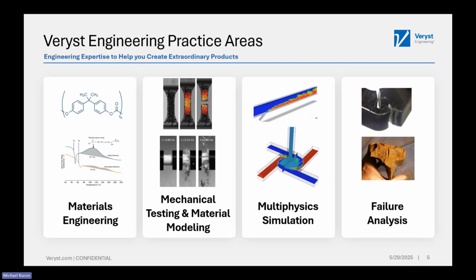We've developed our own in-house test capabilities, including drop towers and high-rate test systems to capture complex nonlinear constitutive behavior of those materials. Almost always an outcome of our work in the lab is a constitutive model for a finite element analysis model. So we work with a lot of clients to develop constitutive models that then either they or we will use for modeling the system or component behavior in a complex manner.